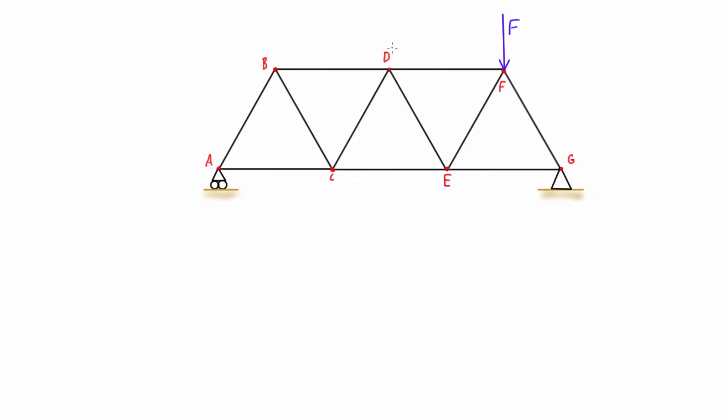We're going to isolate them all and solve them independently from each other, basically like a particle equilibrium problem in 2D, where we'll just sum up the forces in the x direction and sum up the forces in the y direction, and we know all of the forces are going to be in line with the members themselves. And so knowing that, it actually makes solving this problem pretty easy.